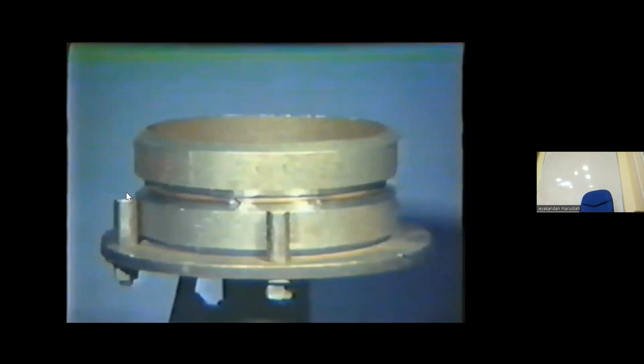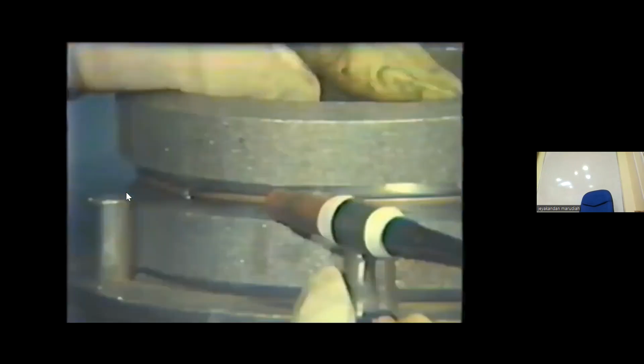Now, place the second pipe nipple against the insert to form the complete joint. The butt face should fit tight against the insert. Deposit small tack welds to join the insert to the second pipe. These welds should be located halfway between the existing tack welds. Start the arc on the first pipe bevel and form a puddle. Carry the puddle across the insert and onto the second pipe bevel. These tack welds should fuse the consumable insert into both of the bevel edges.